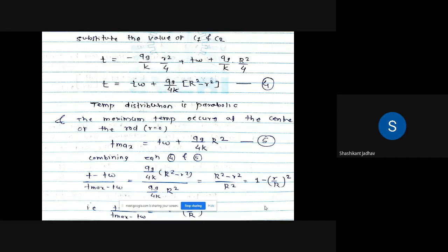So there is one other formula to calculate the resistance. And what is that formula? Resistance is nothing but rho into L divided by A. Resistivity is given, length is known to us, and area is known to us. Using that, we calculate the resistance, and from that we get the value of Q, that is the rate of heat transfer.